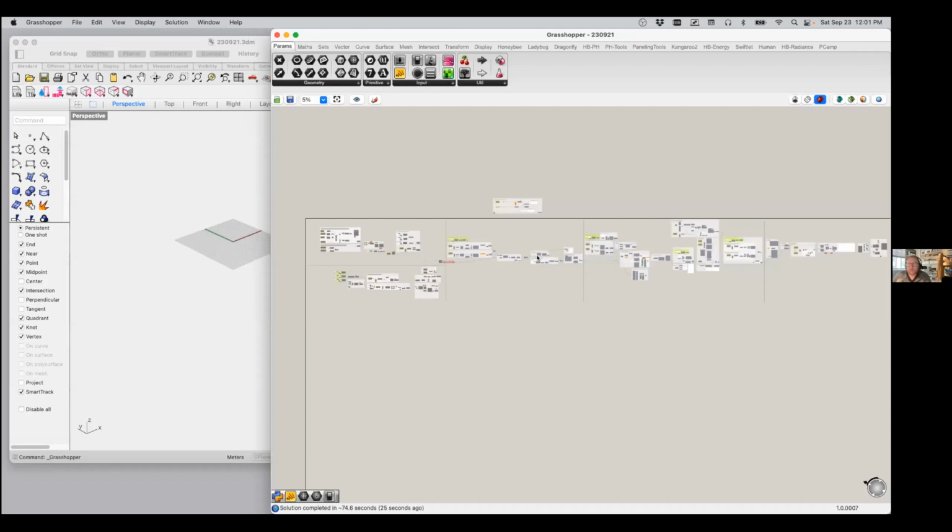It's small things like, oh, that wall in Revit that looks like one wall is actually made of two walls that I smushed together because there's like an outer portion and an inner portion. And so you can't actually consider it one wall. And so when you export it, it comes in as two layers that are like overlapping each other. Small things like that. And then big things, just around where the edges are and what you consider a floor and what's inside and what's outside.